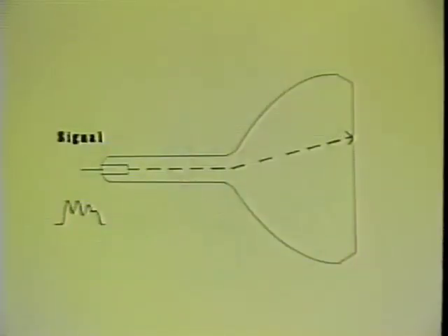A complete array of lines is called a raster. With no picture, it is known as an unmodulated raster. With a picture, it's called a modulated raster. The grays in a television screen are produced by varying the strength of the beam. The beam is varied by an electric signal applied to the electron gun. This signal originates in the television camera, and so now we will turn our attention to this.